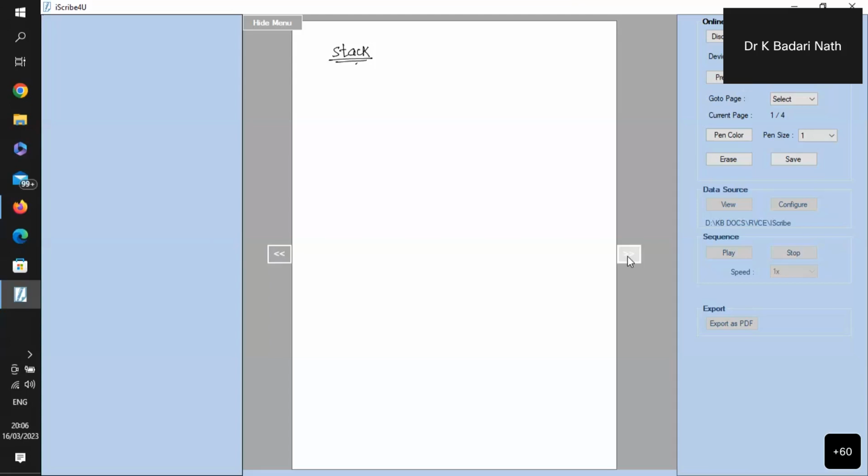So where is the stack provided? If somebody asks where the stack is inside a processor, is it inside the processor or outside the processor? There are certain processors where one register is available called the link register. Only one level of nesting you can achieve, so you can call that a one word stack, but it's of limited usage. But if you want a stack which can be used for storing the local variables, passing the parameters, everything, that stack is popularly called the process stack. What stacks you use in high level language programs is different from what I'm talking about now.